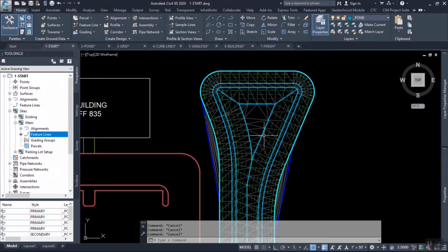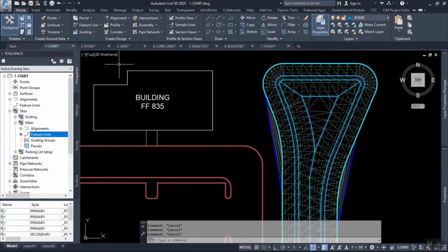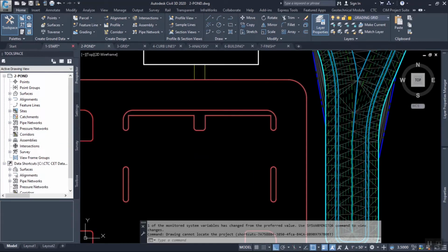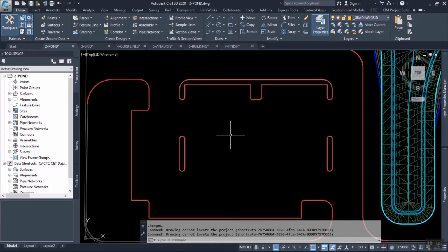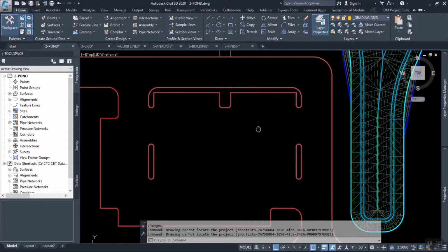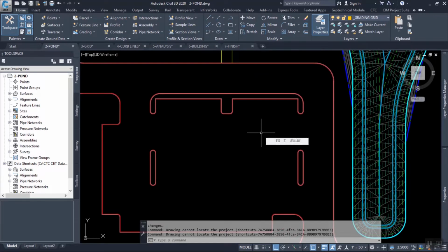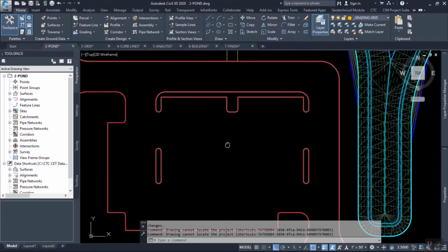We're going to move on to the parking lot. What's interesting about grading parking lots? So much detail, right? All these curb islands and things curving all over the place. It's got to drain this way and that way and all these things. But if you separate the horizontal geometry from the vertical geometry, it gets a little simpler. And what I mean by that is it's the horizontal geometry that's complex. But what's the vertical geometry? It can be fairly simple.